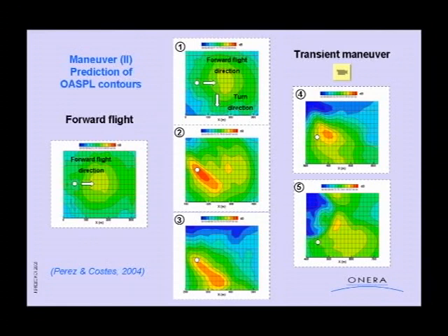and you can see that you have an increase in BVI noise. In fact, this is due to the fact that the helicopter rotor is tilted starboard and it's getting closer to its wake. And surprisingly, the noise decreases. It is due to the fact that as the rotor is tilted starboard, the pilot has to increase the collective to get more thrust to maintain the helicopter in altitude.